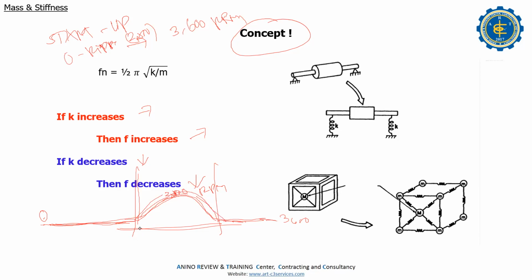You make it directly, because if you slowly climb, slowly drive, maybe the vibration goes high. Okay, you know the point. If you are in charge of this, you must know first the critical speed, so that this time you must jump directly. Then after that, normal operation speed will be achieved. So that's my advice to you. Time will come, you can do it.